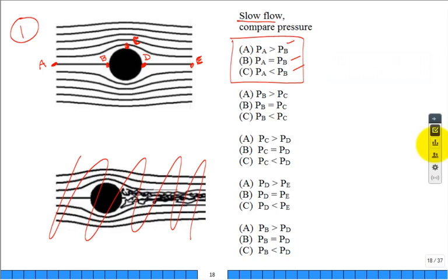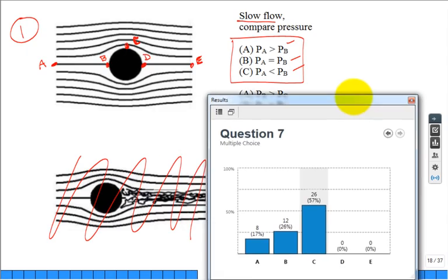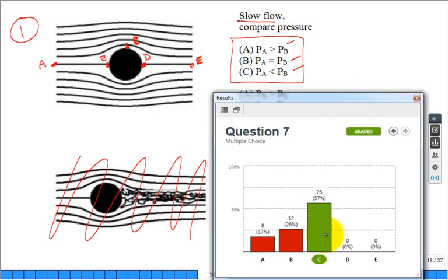All right, well, why are we not more correct? What's happening is that point B is called a stagnation point. When you bring your flow to the stagnation point, it comes to rest and the pressure goes up. It goes up by the amount of the dynamic pressure, the velocity pressure, both names work, 1/2 rho v squared. Bernoulli's equation. True? All right, so there you go.